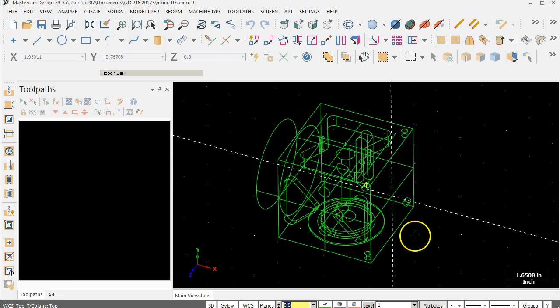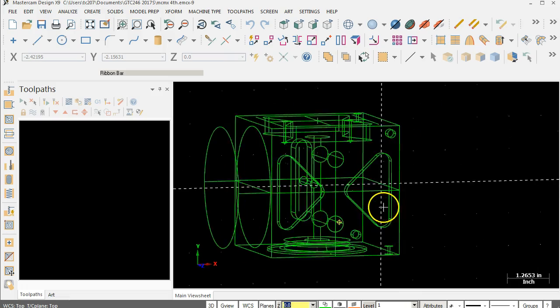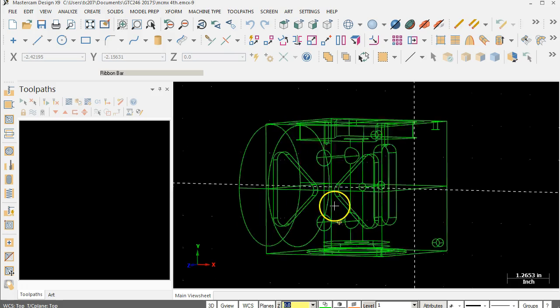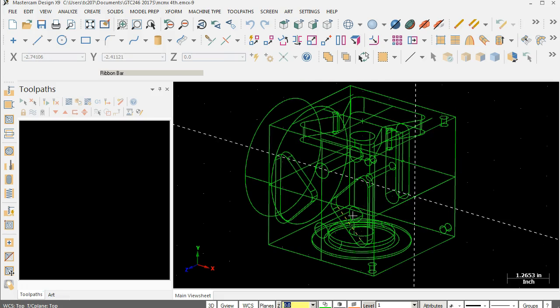Okay. And the issue isn't so much the block, it's that we have all of these wireframe items to sort out, and what is actually the usable entities, what is not going to be as usable. So my first impulse is, if I have solid geometry, if I have the solid module, then I'm going to bypass the IGES and not deal with this. If I do have to deal with this, I'm going to go through and create levels and select individual pieces of geometry and try to limit the amount of selection, limit the amount of items on the screen that I'm having to deal with.